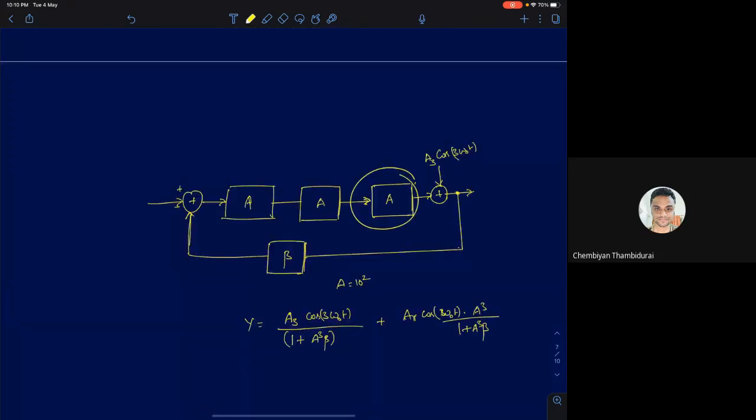I've replaced this amplifier. I'm going to assume these two are linear because the additive components are so small. I'm neglecting those additive components, and I've replaced them with a linear model. Now all three amplifiers are linear amplifiers, and the nonlinear term is being added as a distortion term at this point.